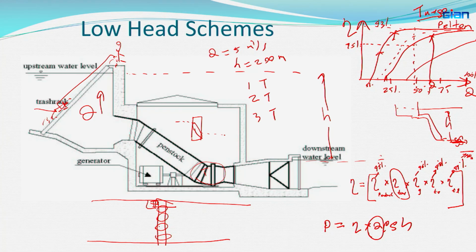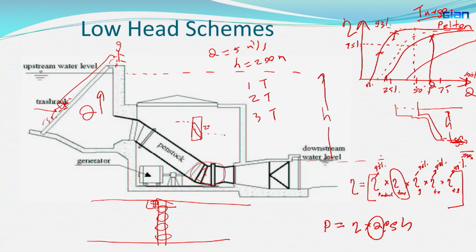But when you have the dam, you have a height difference and the boats cannot pass, so they have to have a separate arrangement. So there's a cost also, with water pumping, etc. Therefore, multiple turbines are possible, and that is being done. I have seen projects with such multiple turbines, in series. These things are done in the last part of hydropower development, because the head is maybe 2 meters or 1 meter, ultra low head projects. But the Q, the flow, is enormous. Therefore, P is high. You can have sufficient power because Q is high.